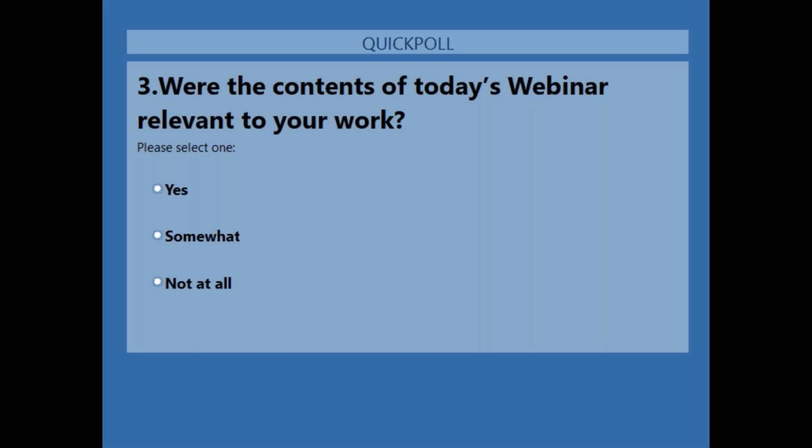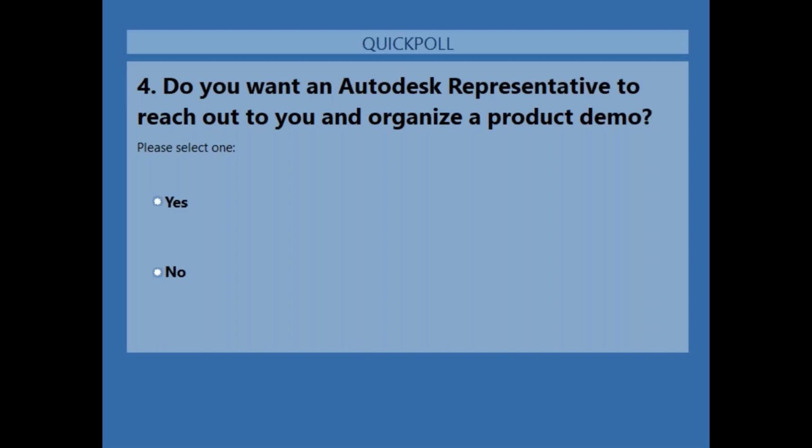Rebar does not directly increase the size of the file, but it makes the file complex, so it impacts the performance of that particular file. When working on rebar, I always recommend working in coarse mode rather than fine mode.